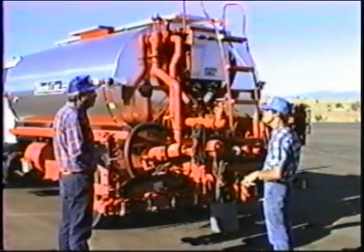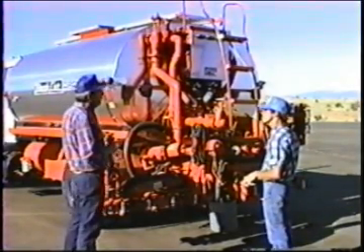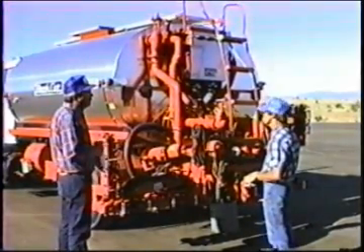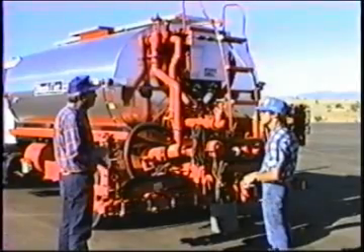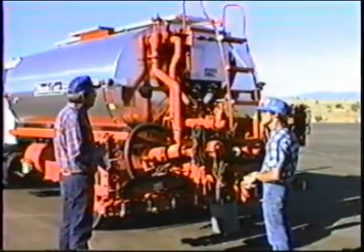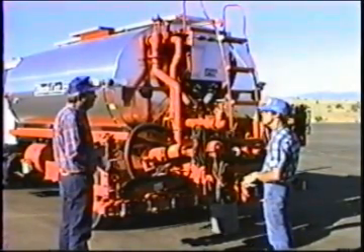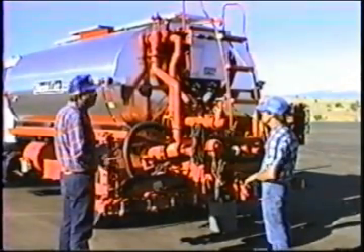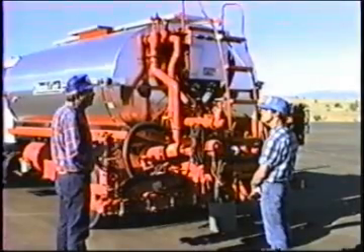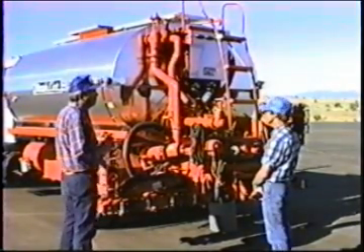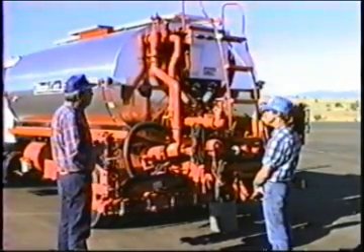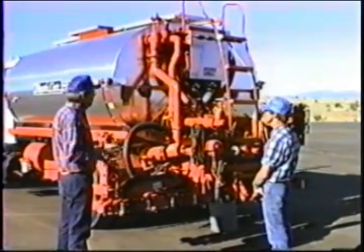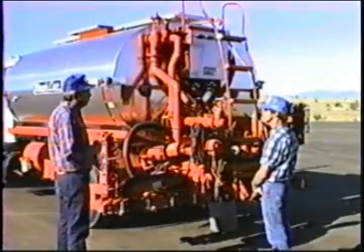If the tank is wet, of course, if you spread emulsified materials and have any idea at all that the next day you're going to spread a hot material, you want to be very careful to totally empty this tank out. Totally empty the tank and the spray bar. Some days it'll come up as a surprise. Maybe the schedule changes altogether, and yesterday we sprayed SS1. Today they tell you to go load paving grade asphalt. Well, that's a surprise. Maybe we didn't get it totally emptied out.